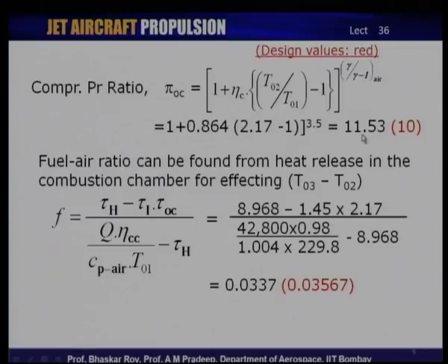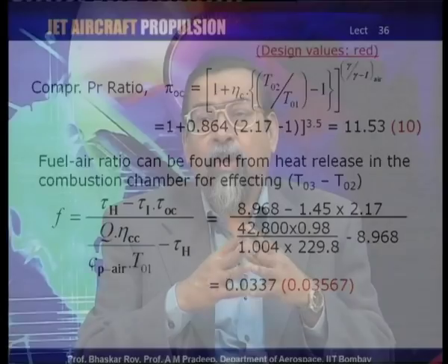Now, this means that in terms of the compression ratio, we are getting more compression at off design condition compared to the design point compression ratio that was prescribed for the engine. This is not totally unexpected, because if you remember the compressor map, it has a design point, but the compression ratio is not maximum at the design point.